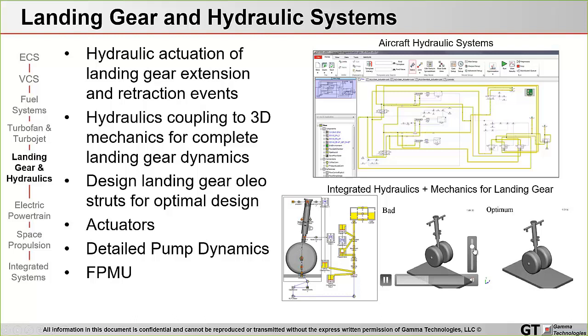As you can see in these animations here, it's set up in a rather extreme case for a bad scenario where, if you're doing a standard drop test, you get some nasty vibration after the original bounce. But homing in on an optimum design, particularly of the valve behavior in the Oleo strut, allows you to really achieve the optimum damping characteristics, so you get a nice smooth landing in a drop test.